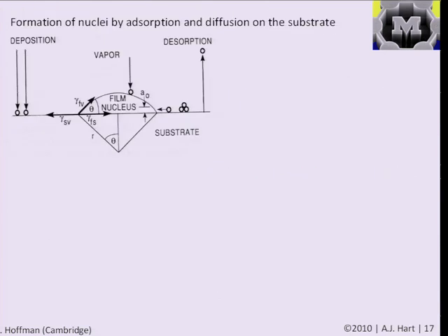So if we think in a vapor process, if we have a substrate on which the material deposits, what the fundamental processes are, we can have atoms coming out of the gas phase and depositing onto the substrate, and then the atoms can either move, diffuse across the substrate, and collect in a particular place and form a nucleus, or they can adsorb and desorb, or they can deposit and diffuse and then desorb as well. And just as we thought in the gas phase in the room here of passing this critical concentration of precursor, the same thing can happen on the surface.